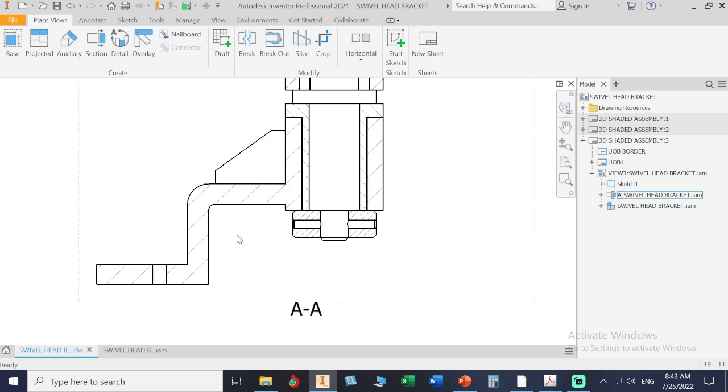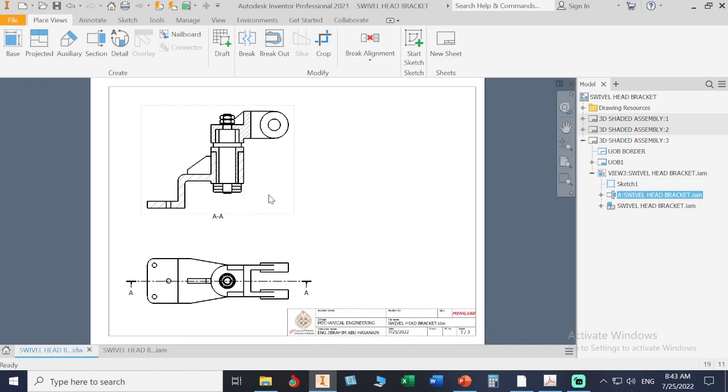That's why we created 2 solids. Do you remember? And we have 2 hatches here. If you don't create it as a solid, this line and this line will be removed, and it will be one part with 1 hatch. This is what we don't want. We want to define our web.